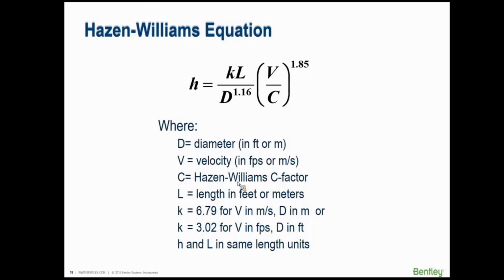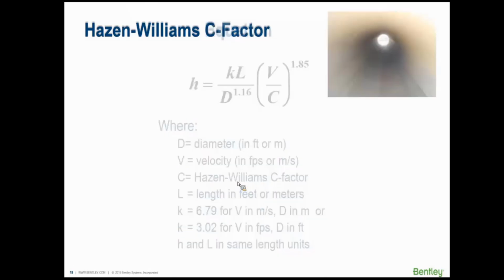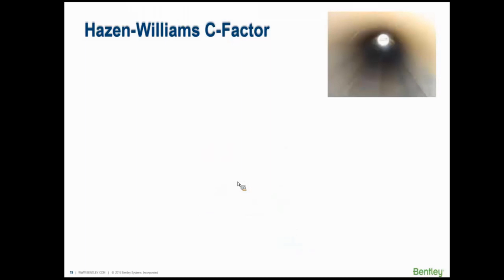There are a lot of caveats to that as well, but it's a pretty good parameter to have. So people like this, and they still use Hazen-Williams a great deal. It really depends on how much carrying capacity the pipe has, so it's not a measure of roughness as the Darcy-Weisbach f is. It's a measure of carrying capacity or smoothness of the pipe. And you can measure this with tests in the field or back it out during your model calibration.